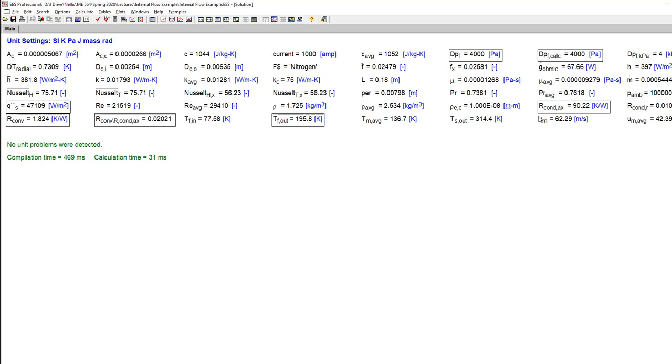Now, if I would have done the same calculation and found that our axial conduction is like 0.01, so substantially smaller than this one, then I have a problem because my assumption is wrong. Then I have the opposite situation, where my entire current lead is going to want to become isothermal because it's easy for energy to move back and forth axially. My boundary condition really should have been constant temperature. I would have a constant temperature current lead.